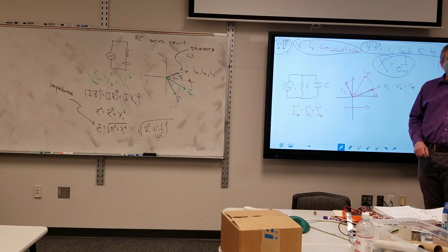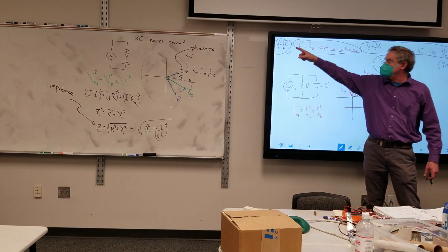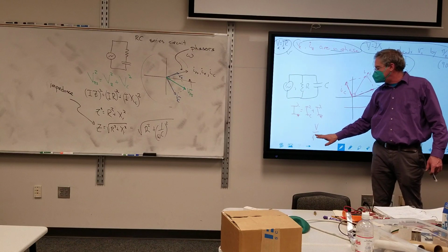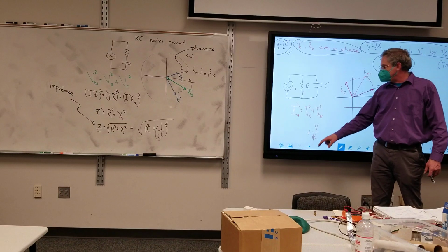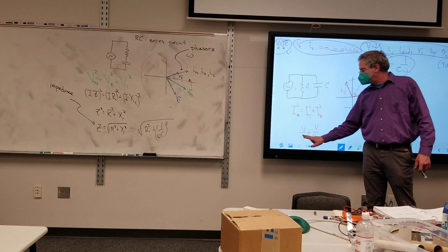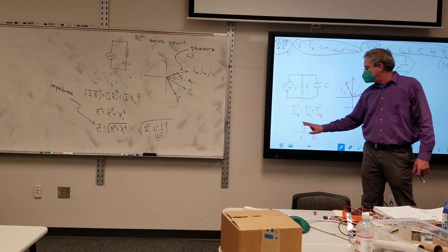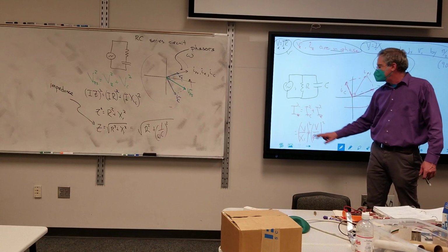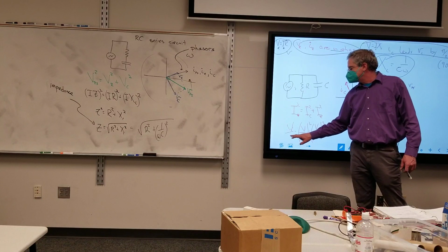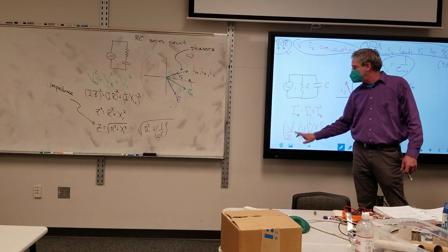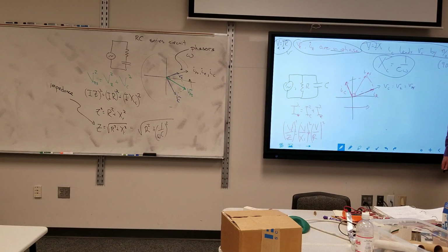Okay. All right, so now let's exploit our Ohm's law variations. I know for current, I is V over R, so this is V over R. I know the voltages are the same, so I'm just going to use V for it. For capacitance, that's V over X sub C, squared. And for the power supply, that is V over my impedance, all that squared. Therefore, 1 over Z squared is equal to 1 over X sub C squared plus 1 over R squared.